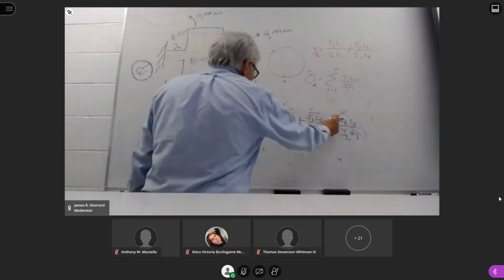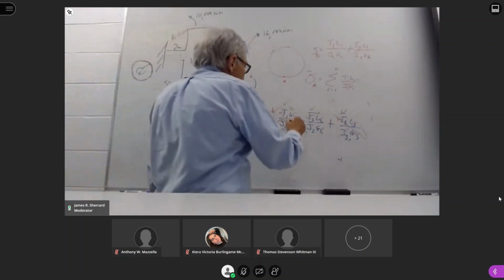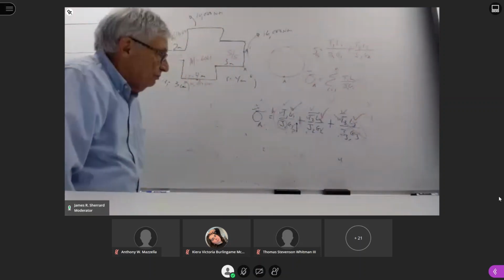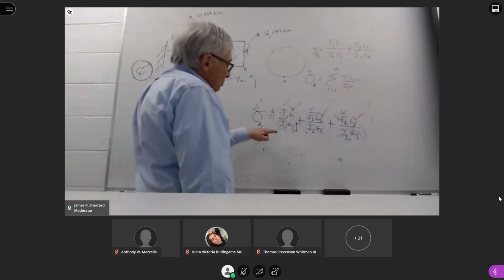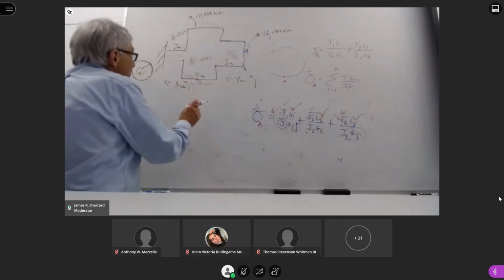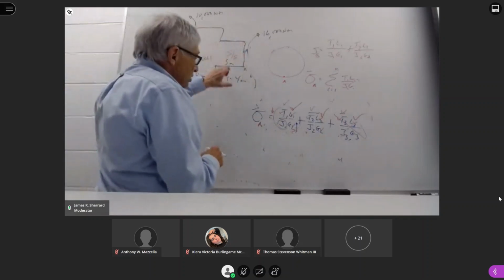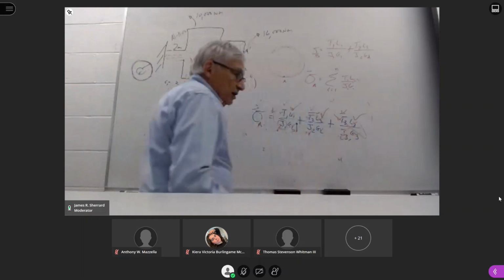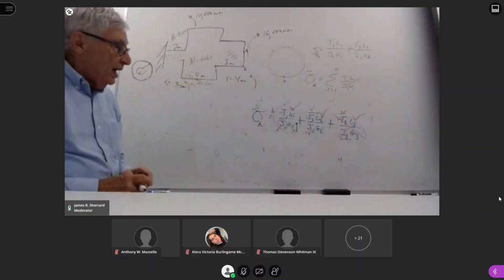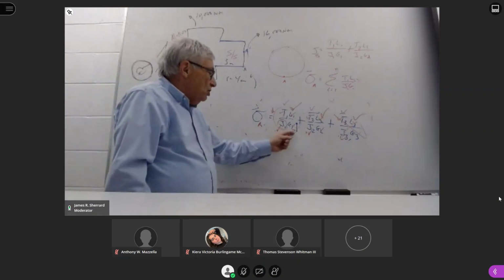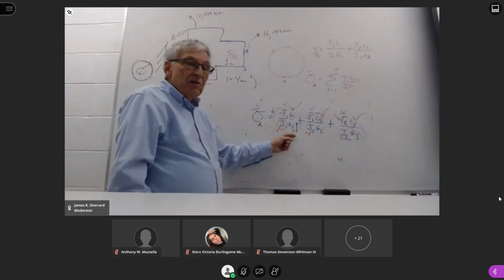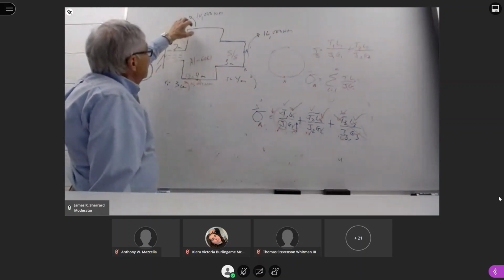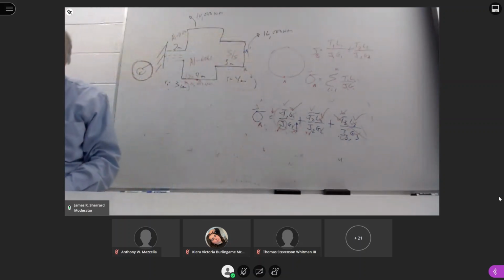What about the lengths of each? They haven't changed, so all of those are exactly the same. The polar moment of inertia for each region: the cross section has not changed, so each of these has not changed. But what has changed is the modulus of rigidity for each section, which now has to reflect the physical property of the material in that section.